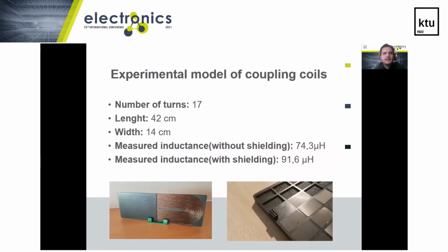The designed model is made using a 3D printer. The experimental model consists of 17 turns. The length of the board is 42 centimeters. The width of the board is 14 centimeters, and with ferrite shielding, the measured inductance value of the model was 91.6 microhenry.